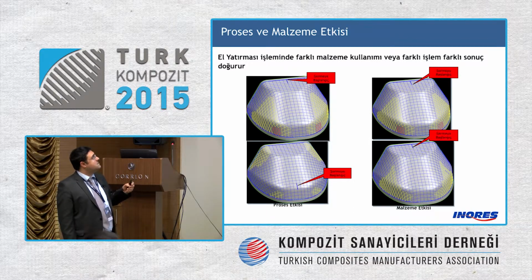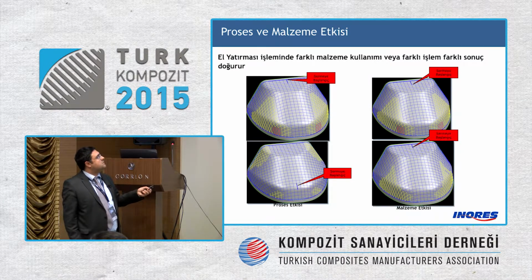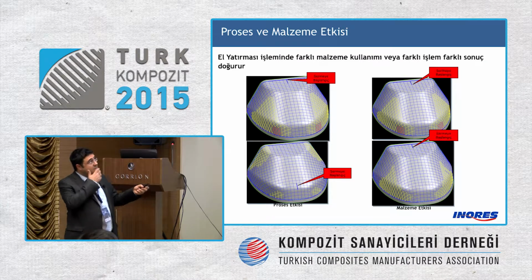Another issue in fabric prepreg systems, for instance, there might be some challenges on the red parts over here. Creasing might occur. You might have to take some precautions. Or if you start putting the fabric from here, there will be no creasing.